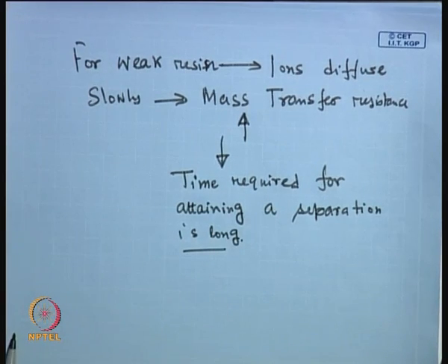So, these are the various advantages and disadvantages of weak and strong resins, acidic resins and basic resins. Now, let us look into the binary ion exchange equilibrium.